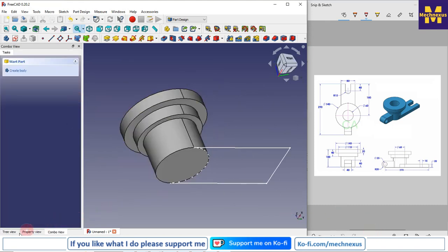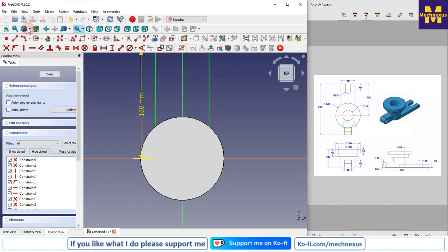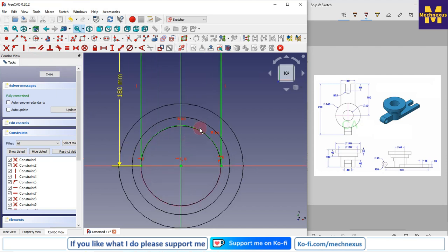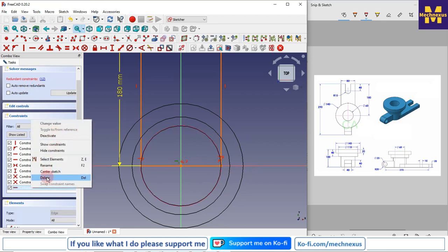To overcome this error, we will edit our sketch and switch to the wireframe. We will delete this line and join this line here, and we'll remove this conflict.